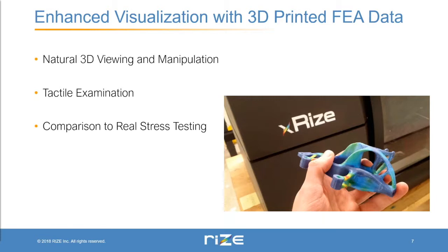So that would be the Z axis is about 90% as strong as the X and Y axes, and this is quite good for 3D printing in the thermoplastic world. So in our case, we would be able to use this technology quite effectively to test whether the results of the simulation are mapped accurately onto the eventual part.